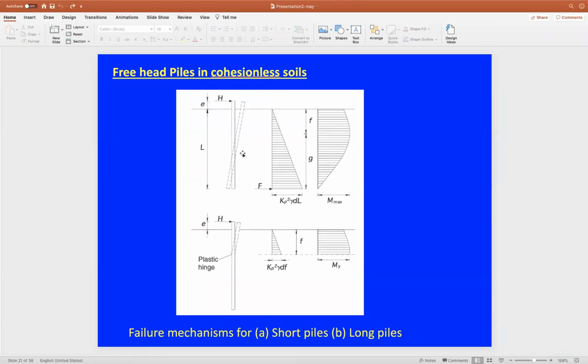as with last week, the external diameter of the pile is 305 millimeter, and the shell thickness is 19 millimeter here. So by doing so, we're gonna work out the internal diameter of the pile. And after we did that, we obviously need to draw the reactions or the distributions of the forces in the problem. As we can see in this figure, we have the ultimate horizontal force at the head of the pile, and we have the soil reaction here.